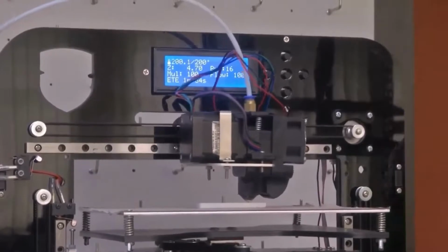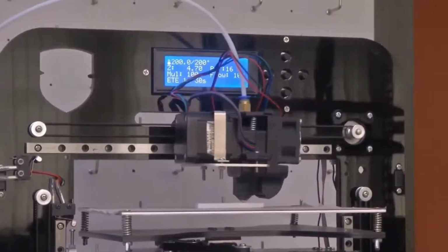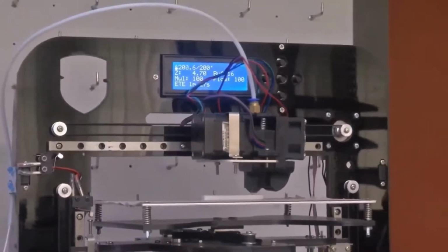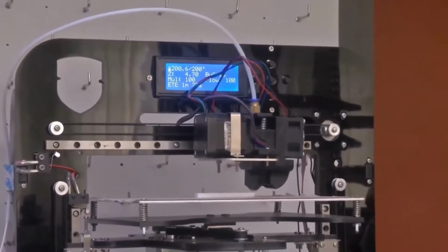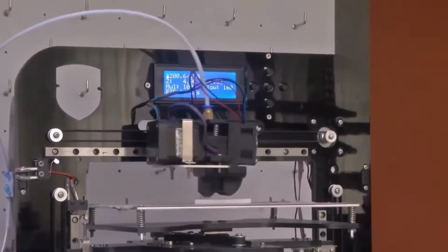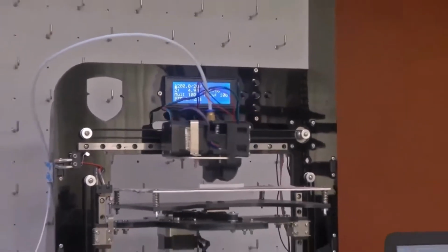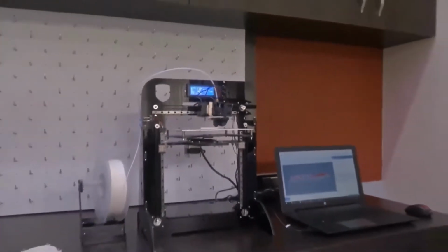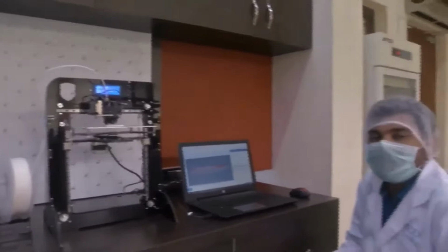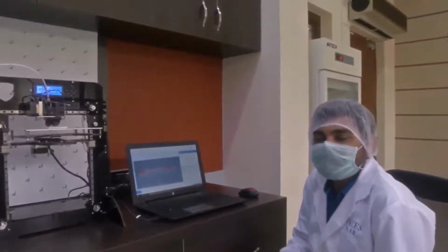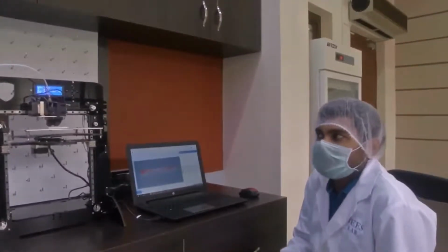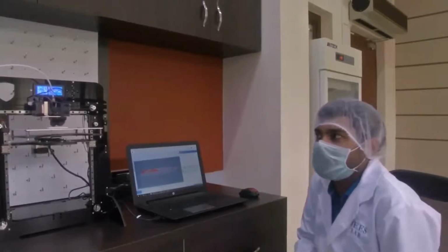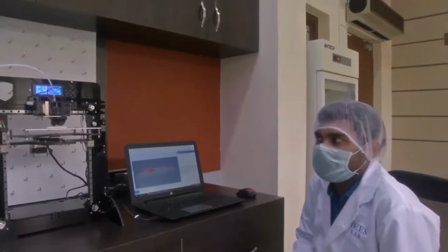Because ours is not a very high-end 3D printer, it's very important that we need to have a continuous power supply. In case supply goes while it is getting printed, it doesn't have memory to restart printing. So that is one shortcoming. Higher grade printers have that option. So it's better that you have a backup power supply for these printers. When it's about to get finished, we will focus back again on the printer and you will see the platform dropping down.